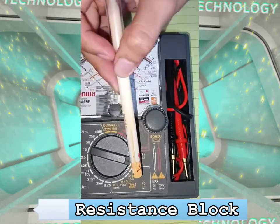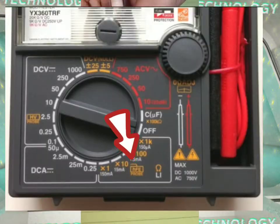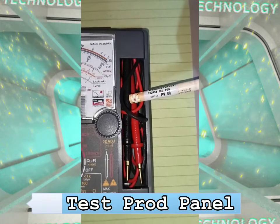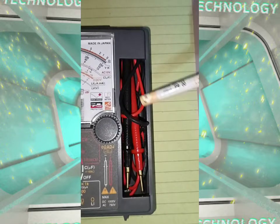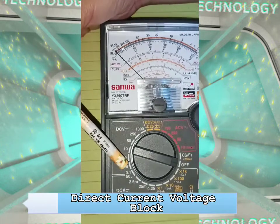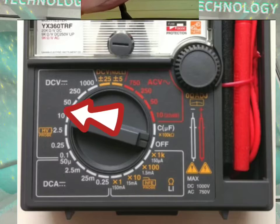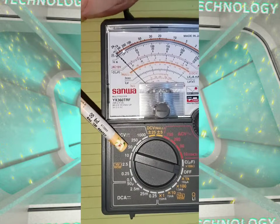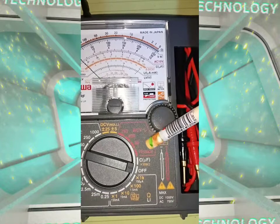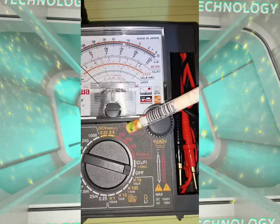One is the resistance block. From here to here, the orange one, is the block used when measuring the resistance or continuity of an object. One is the test rod panel. It's the case of the positive and negative test rod. The next one is the direct current voltage block. From here to here, it is the block used to check the polarity of a battery. The next one is the alternating current voltage block. This one, the red one, is the block used when measuring the voltage of an object.